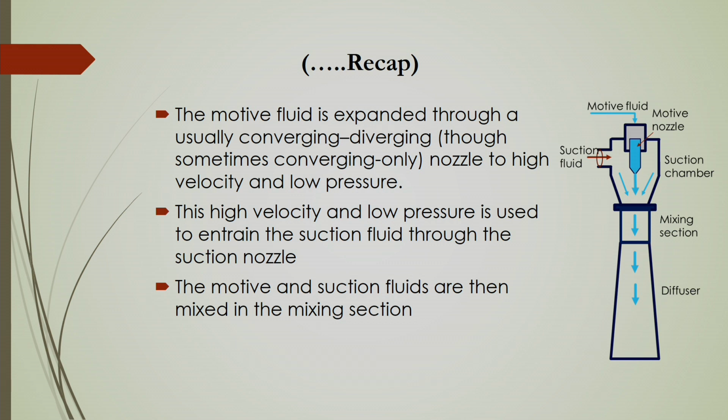And also we have discussed that the motive fluid, whenever it is expanded through a usually converging diverging section of the ejector, the nozzle gives you a high velocity, and because of which there is high kinetic energy and formation of low pressure, as per Bernoulli's equation. Then the high velocity and the low pressure are used to entrain the suction fluid through the suction nozzle, and the motive and suction fluids are then mixed in the mixing section.